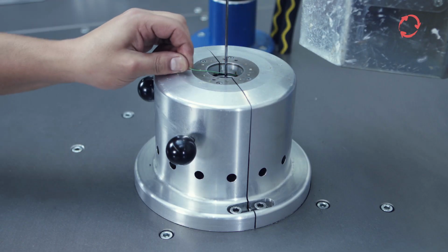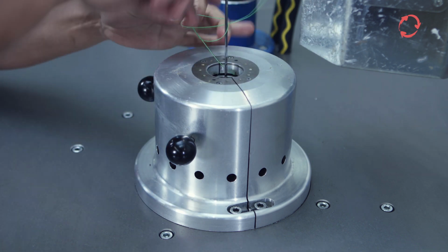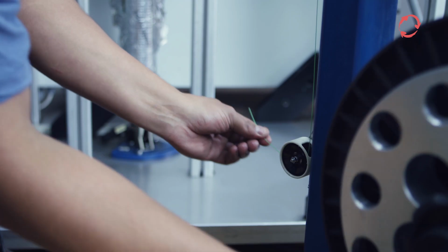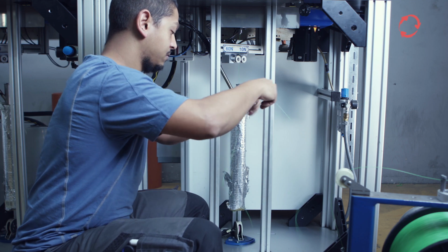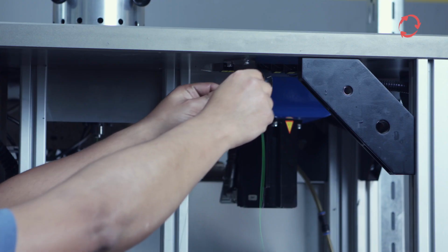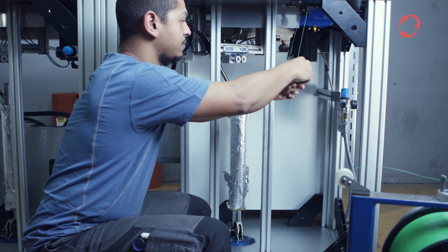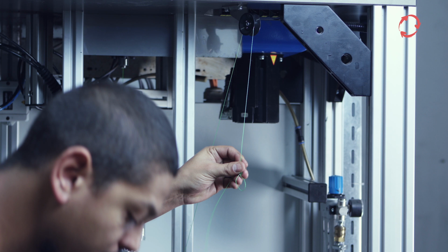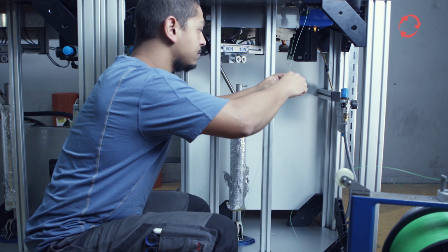Pull the spiral wire as described in the chapter Feeding the Monofilament into the Machine and tie it to the spiral mandrel. Take the spiral wire between the 4th deflection roller and the tangential unwinder and feed it over the deflection roller mounted under the machine tabletop. Now the spiral wire on the tangential unwinder is cut off about 50 centimeters below the deflection roller and knotted into a loop. First, the 10 Newton sensor is calibrated with the smaller weight.